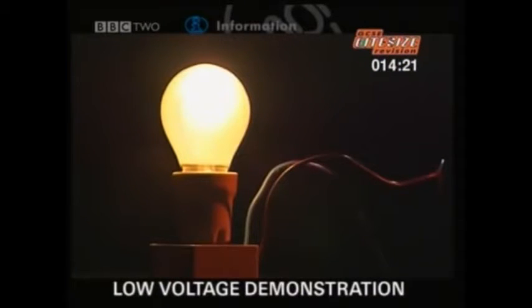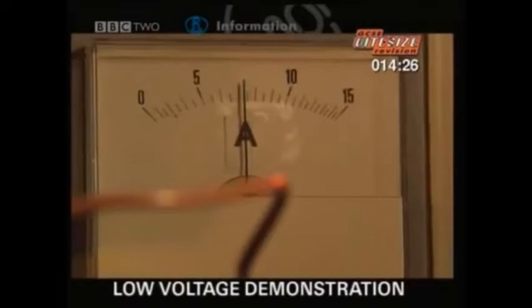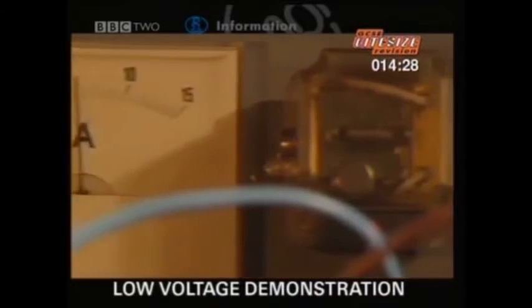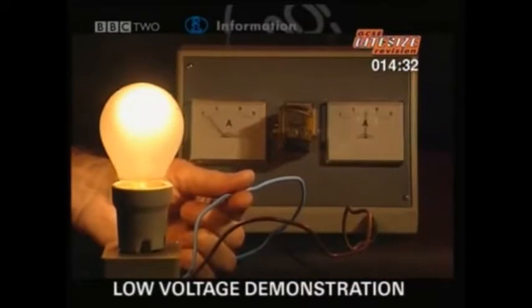All circuits have 2 connecting wires. The current flowing in each wire should always be the same. If you accidentally touch a bare wire, the leakage is immediately detected by the RCD, causing a switch to trip.